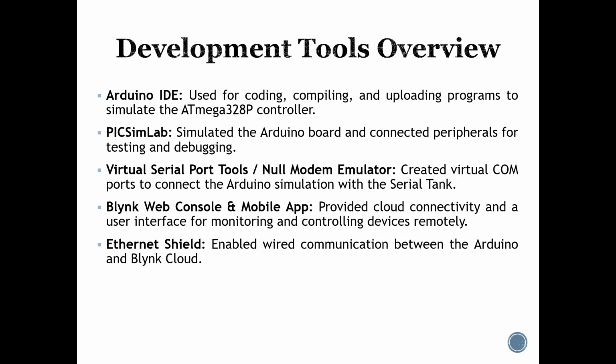Next, development tools. For development, I used a few essential tools like Arduino IDE, which I used for writing and uploading the embedded C and C++ code. PICSimLab, a simulation tool that replicates Arduino hardware and allows testing of the code virtually. A virtual serial port emulator, or virtual serial port tool, to create serial connections between the Arduino and the simulated tank. Blynk IoT apps and web consoles to monitor and control devices remotely via cloud communication.